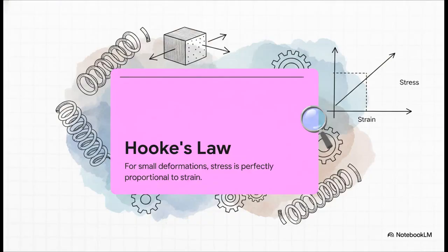This brings us to a massive, absolutely crucial concept for your exam, Hooke's law. Back in the 17th century, Robert Hooke figured out that for small deformations, and remember that part, small deformations, the restoring force per unit area, which we call stress, is perfectly proportional to the fractional change in dimension, which we call strain. Put simply, stress equals a constant k times strain. That k is the modulus of elasticity. It's an empirical law based on observation, and it works for most, but totally not all materials.